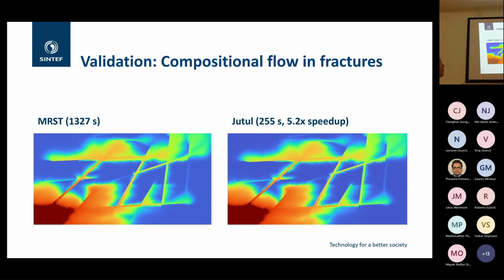Similarly, we can solve a problem that's coupled to multi-component flash. This is a smaller model representing fine scale resolved fractures on an unstructured mesh. You are injecting CO2 into a mixture, basically the SP5 mixture that we used as the benchmark. You see high speed of movement through the fractures moving up, and a sort of two-phase condition in the middle of the model, followed by a sharp shock where you have complete CO2 and complete miscibility due to the relatively high pressure of injection here.